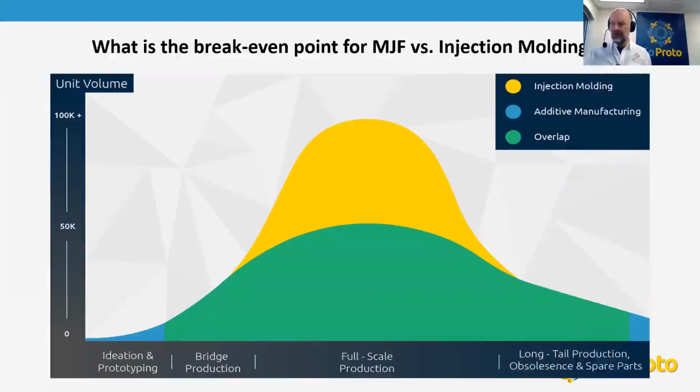Beyond there, no question, injection molding is still going to be more cost effective. So if you're doing mass production, 3D printing is still a cost, I wouldn't say prohibitive necessarily, but it's definitely a higher cost. So we often get to a point where we'll quote both and talk about your design considerations, because as soon as you enter other considerations like design, maybe you're going to be doing mass customization, where you want the same basic design but you're tweaking each one slightly to meet a customer need. If you're going to be changing your design often, and you would have to make tooling modifications for injection molding, then this calculation will change. But in general, we would like to show that as you go up toward 50,000 or so, and in your stage along the horizontal axis, you'll see where the processes fit, and we can help you go through that analysis.